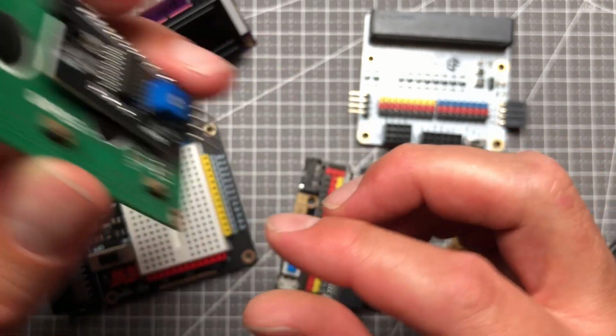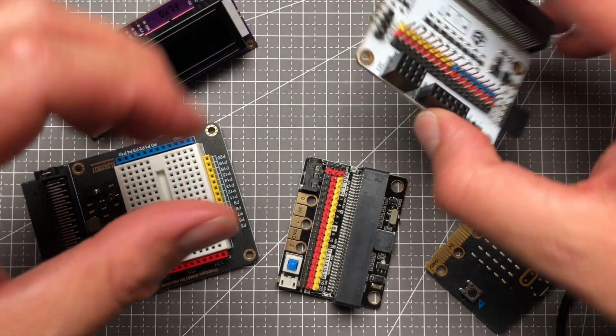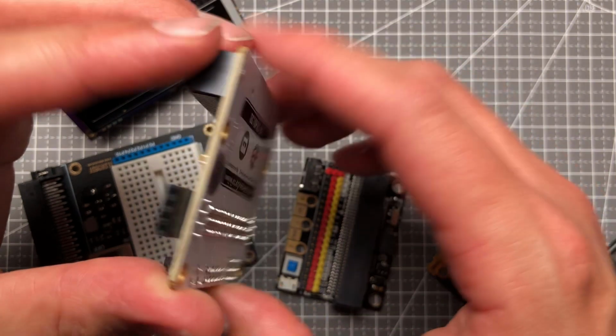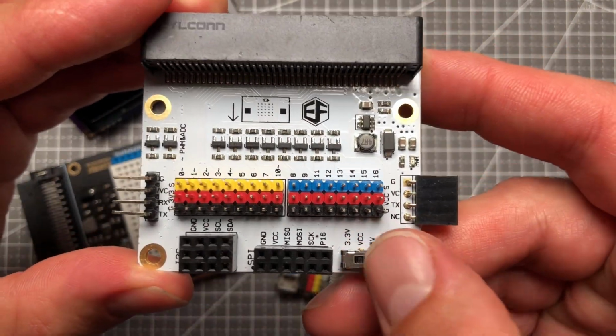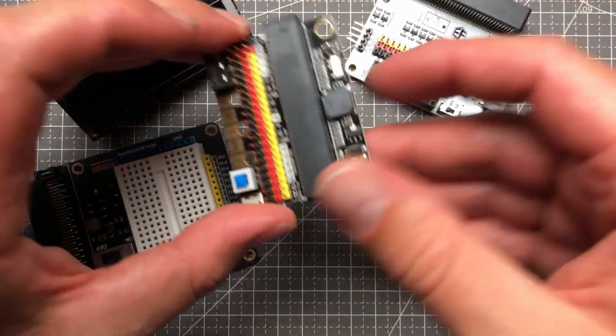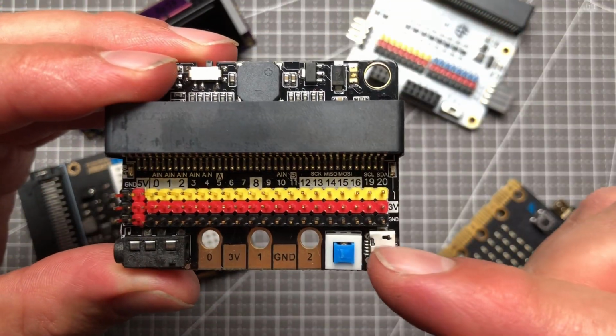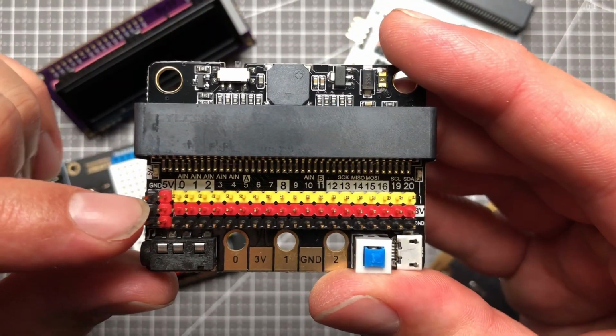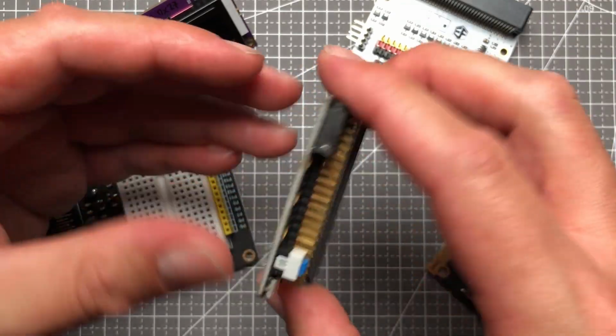Thankfully there are many boards available for the Microbit that actually get you 5 volts. For example, this one where you can actually switch between the 3.3 volt and 5 volt logic, or this one where you can provide additional USB connection and you can get this 5 volt for certain pins. The other option is of course to get the 16:2 character display that is made for 3.3 volt logic.